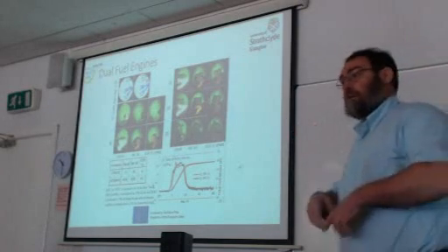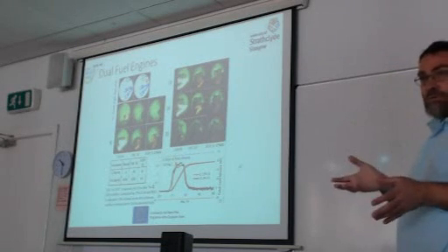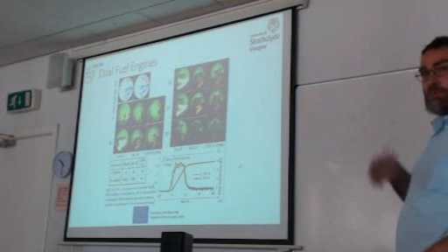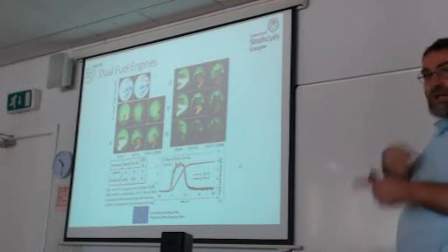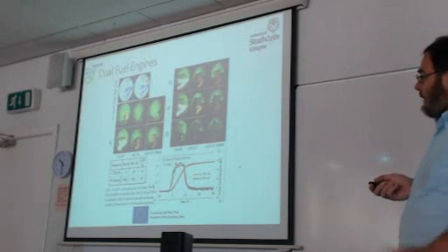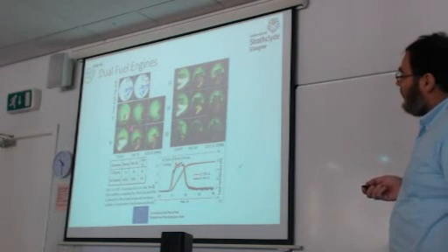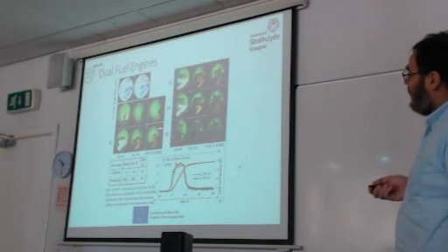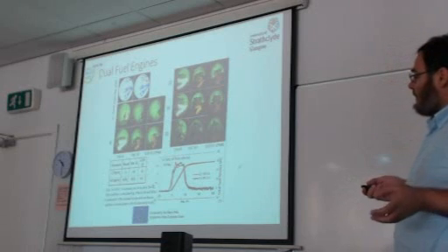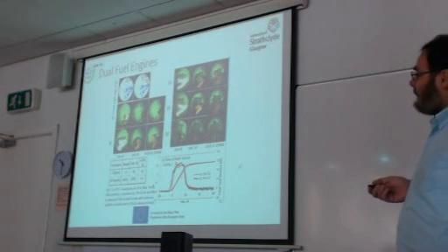And then, in this case, you can see here that we have the gas fuel and the pilot fuel. So certainly the combustion will be initiated by the pilot fuel. So we have again development of the jet, breakup, I mean about the liquid fuel, the pilot fuel. It's a liquid fuel, injected in liquid form. So the spray is developed. It breaks into small drops, and the small drops break into smaller drops, and there's a mixing process around the periphery of the jet. And when the mixture is found in appropriate conditions, combustion will start. So you can see here various frames for this type of process, which of course is more complex.